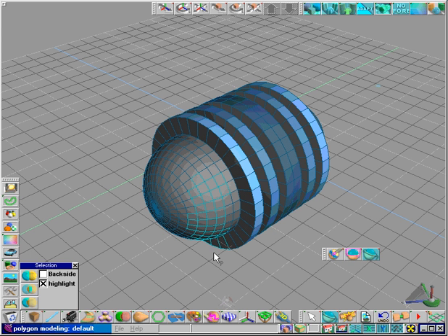The last method is the lasso selection method. With a click and drag, this method produces a freehand curve that defines the selection window. The curve does not have to be closed to select features. Like the other methods discussed, releasing the mouse concludes the selection. Like the rectangle selection tool, a new selection will undo a previous one while in the default mode.